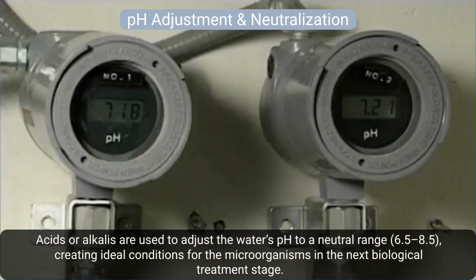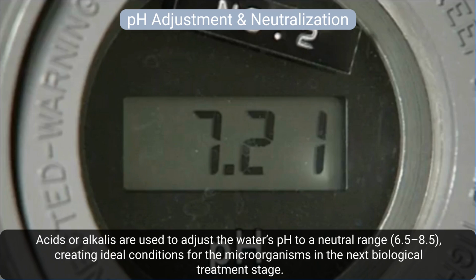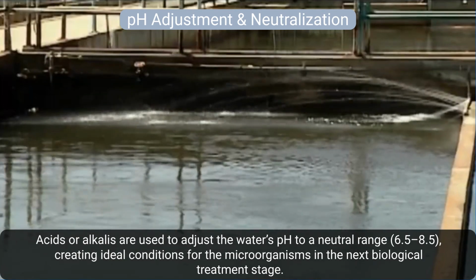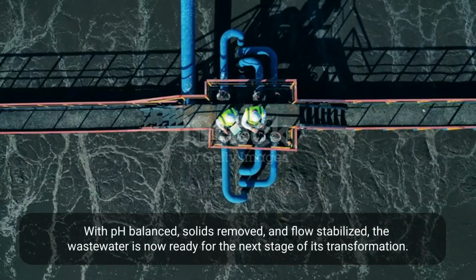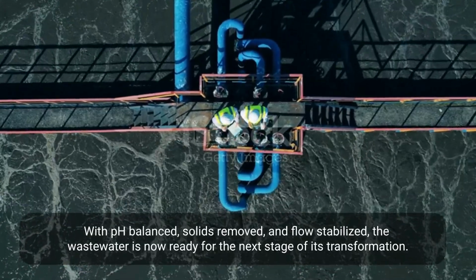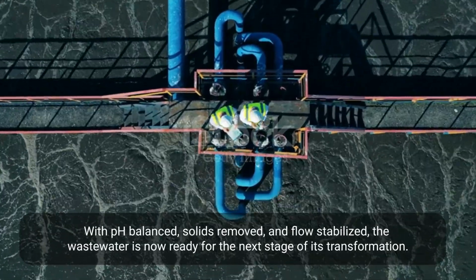Acids or alkalis are used to adjust the water's pH to a neutral range, 6.5 to 8.5, creating ideal conditions for the microorganisms in the next biological treatment stage. With pH balanced, solids removed, and flow stabilized, the wastewater is now ready for the next stage of its transformation.